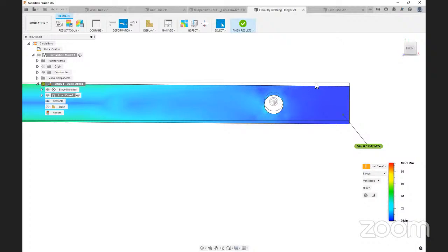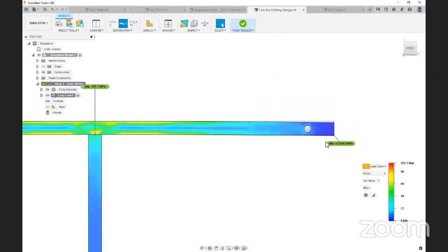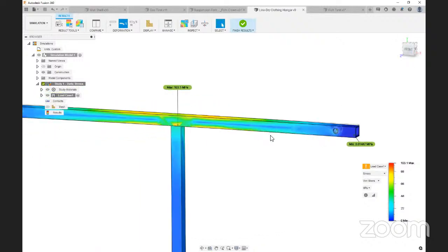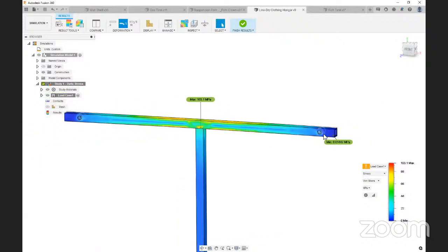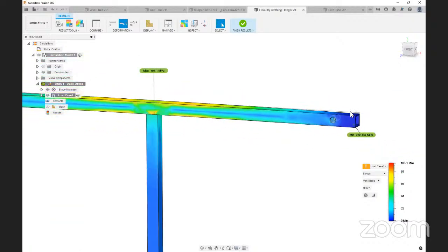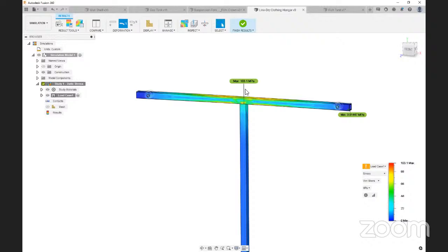It is going down a little bit because it's bending a little bit, but it's not by much. So that's when I would apply a bearing load, is whenever there's a cylindrical face, and then there's gravity that's helping with the force of it, or it's being hung onto this, like some wires, for example.